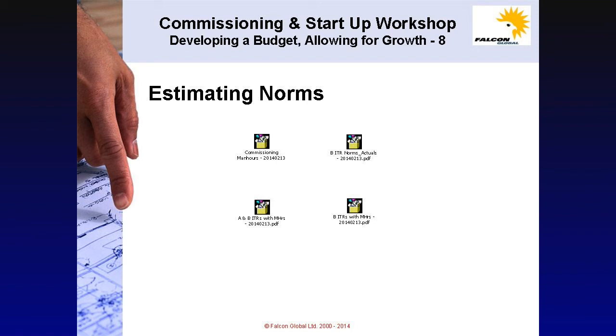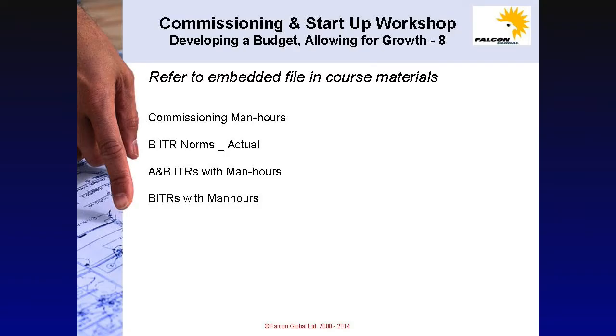The average number of direct man-hours to commission an average system as recorded on a C check sheet or commissioning procedure will be in the region of 250. Extreme caution is needed here, as we know that complex systems such as power management and gas compression can take many times longer to commission, while some systems such as utility air or potable water will take much less. Therefore, the figure of 250 man-hours is an average over the entire project.